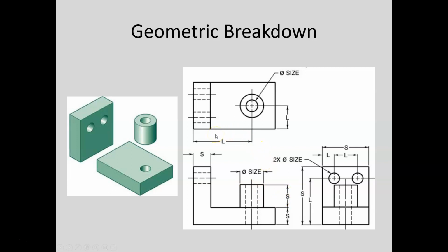Now, when we turn our attention to location dimensions, you can see that we need to locate this hole and cylinder, right? So we locate it from the back edge here and we locate it from the side.